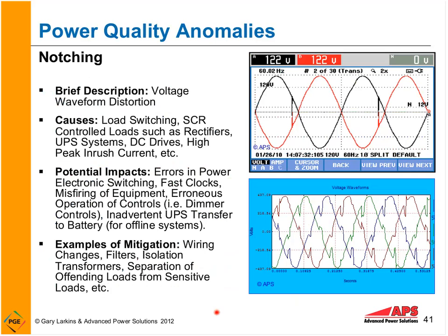Now, what we also have seen in some cases is actually a little funny case study that there was a large plant that was actually causing notching from the rectifier systems. It was causing the farmers' clocks to speed up because the clocks were using the zero crossing of the waveform to actually control the clock timing circuit. When we had extra zero crossings, we saw those farmers getting up at 3 when they meant to get up at 4:30. Not fun.